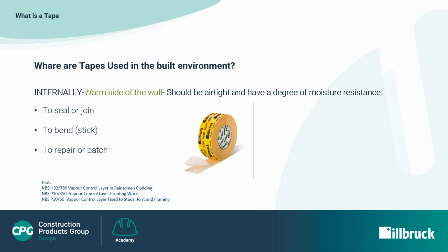Some common uses for internal tapes are to seal or join overlapping seams of monolithic coverings, to bond or stick perimeters or loose edges of monolithic coverings to a substrate, and to repair or patch accidental damage on a monolithic membrane. Illbruck tapes are not substitutes for proprietary internal or external window, door, or curtain walling perimeter sealing membranes.